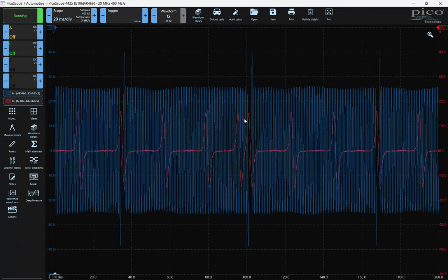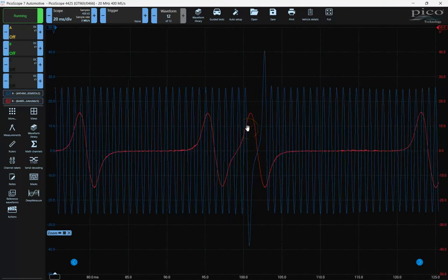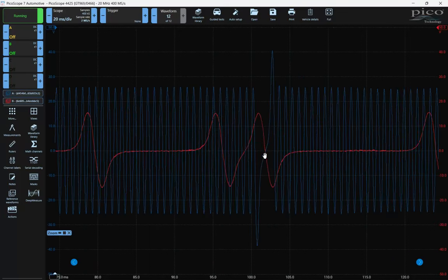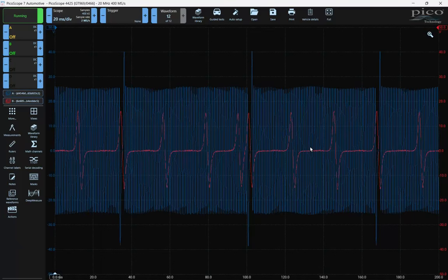So here we can see that sync pulse, as it's called, is coming in. We can see that this is the cam position sensor. This is the crank position sensor. And I know from John Deere, what is desired is that the cam position sensor, where it zero crosses, so it crosses 0 volts at this point, falls within that gap. And so if everything's done correctly, we would see this pattern. If the cam and crank were out of time, or we had a problem with the target, that it had moved or drifted, we would see that this signal would be moved in time relative. So this is another great use of an oscilloscope. Obviously, with your digital multimeter, you couldn't begin to do something like this.